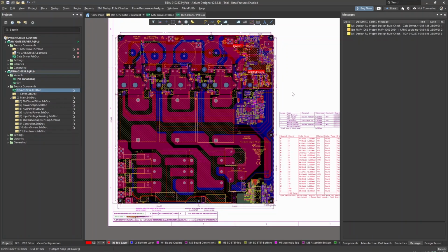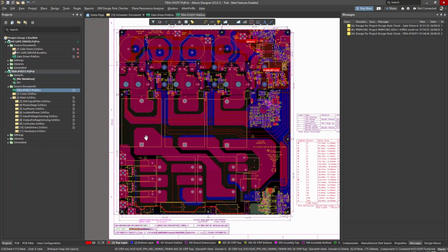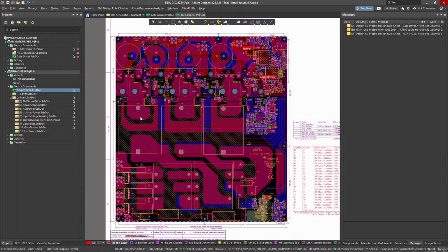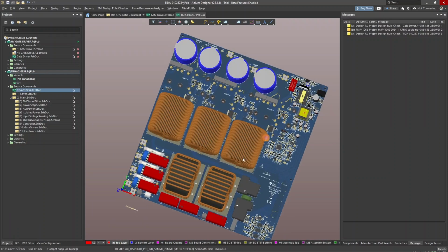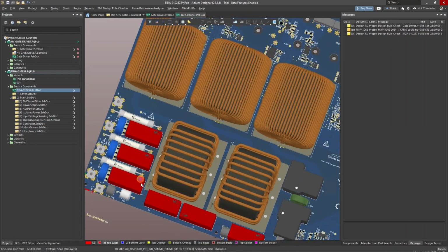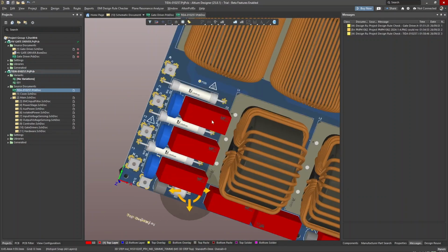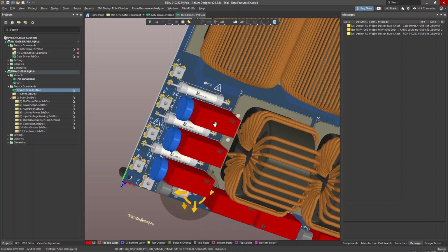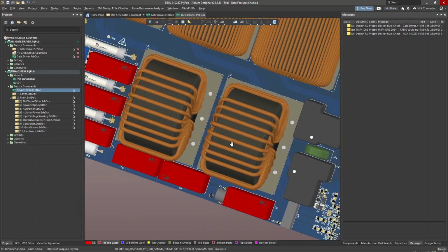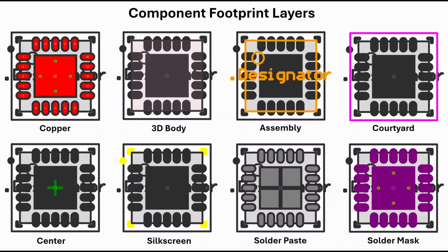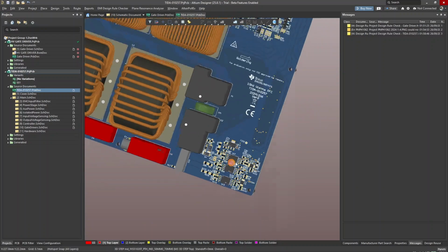Dear electronics enthusiasts, as you can see, Würth Elektronik's libraries are a treasure trove. Don't just take my word for it. Download these libraries and experience their values for yourself. I have found that the database versions of this library are particularly beneficial due to the extensive support they offer. Meanwhile, just as a warning, never ever trust any library blindly. Please kindly check for pin orientation, thermal pad, drill size, creepage and clearance before use.